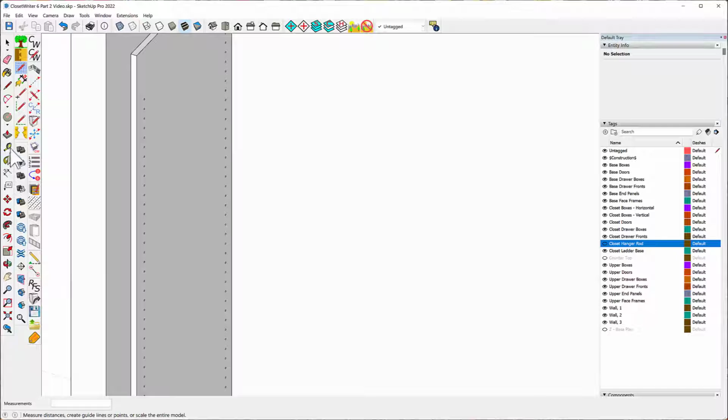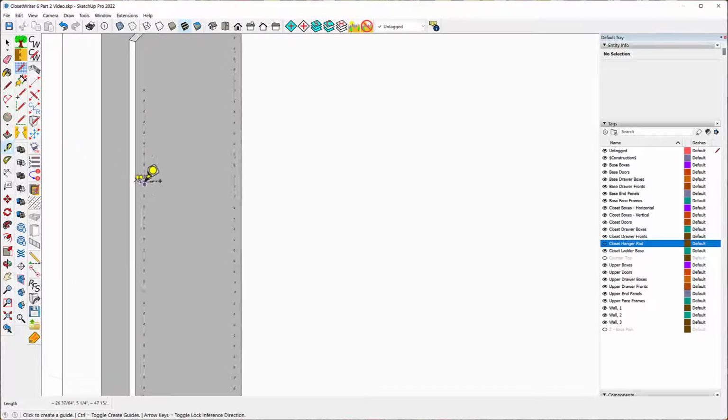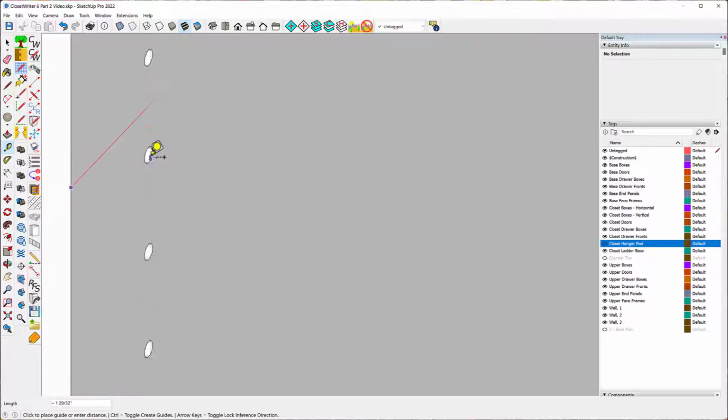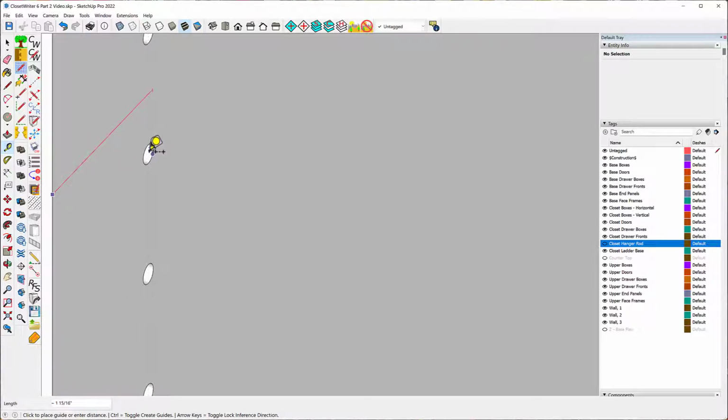The other thing I did, and I mentioned this in that section that I told you to read, is if you look at the front hole setback, well, I'm just going to create a line here that's 47 millimeters back from the front edge. You'll notice that's where the shelf holes go through. Normally the shelf holes are 37 millimeters back from the front.